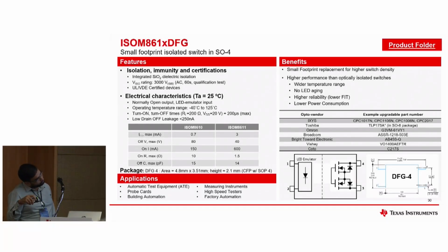Once the device is on, how fast of a signal can go through this? Because once the device is on, this channel is conductive. So that bandwidth is close to 950 megahertz. So 950 megahertz of a signal can be passed through this channel.